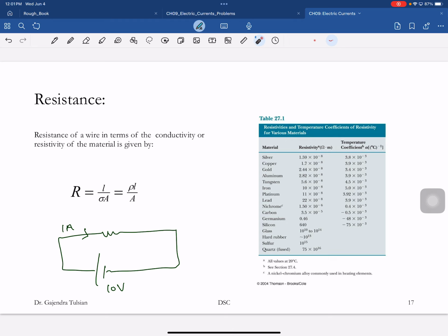So that's why you wear rubber-soled boots. Okay? You catch a live wire, you know. If you're wearing a conductive boot, then your body has low resistance, and current will flow through here. And that current flowing through here might stop your heart. Now, if you have a rubber boot, you've got a large resistance, and the current won't go through here, it will find some other way to go.